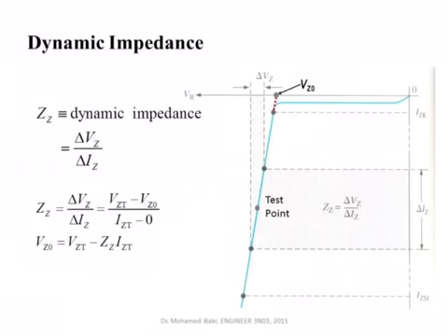As I explained to you earlier, in a diode, if you take into account the slope of the characteristics of the diode, this slope effectively represents the resistance. And you can get this resistance from the data sheet of the diode. So if I give you this curve and then I ask you to find the equivalent resistance represented by this Zener diode, you have to take one point here and the current and determine the corresponding voltage. One point here, the voltage, determine the corresponding current.